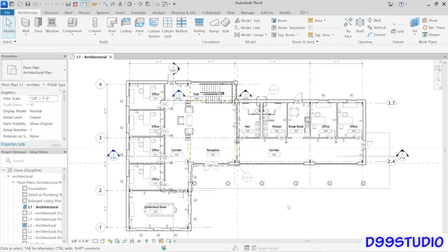In this video, I'd like to show you what I consider to be a better alternative. We're going to look at something called display filters. Now, display filters are somewhere between what we were doing with Visibility Graphics and what we were doing with element level modifications, because they're more parametric like Visibility Graphics is, where Visibility Graphics applies to the entire category in a view. The filter applies to a collection of objects that meet a certain criteria that you get to establish.